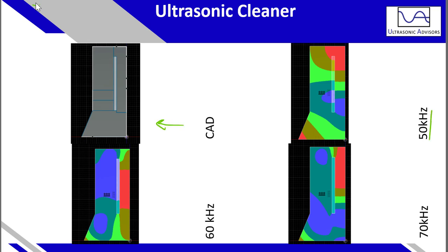Here's the resonance occurring at 50 kilohertz, which is the dominant longitudinal mode. You have higher stress at the piezo, so it's going to provide more effective oscillation there, more effective driving of your device, that will cause your impedance to decrease. Why does the impedance decrease at the resonant frequency here? And why is it the lowest when putting your piezo right at the nodal point?